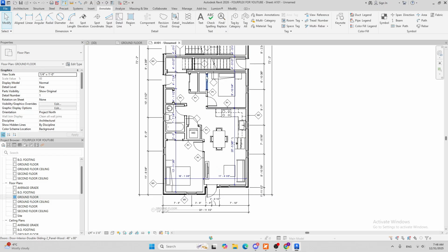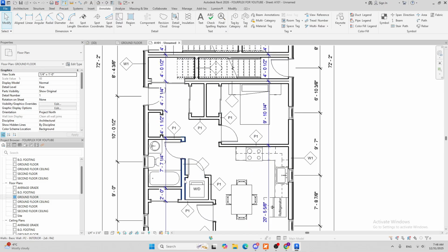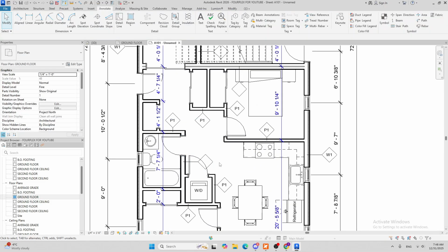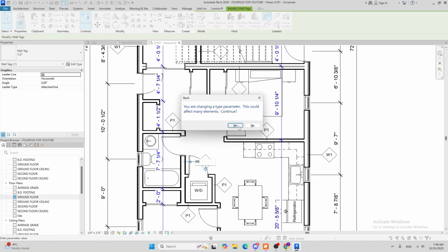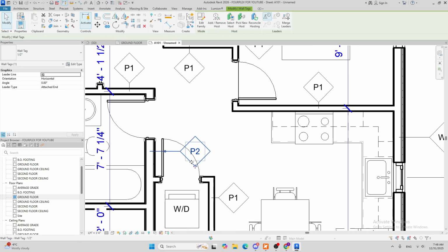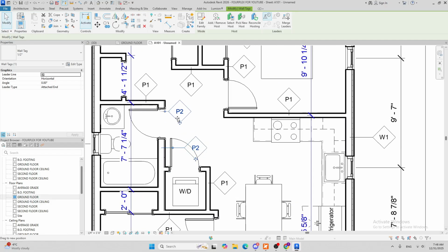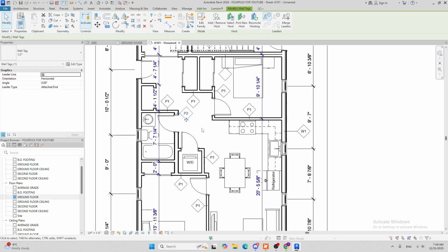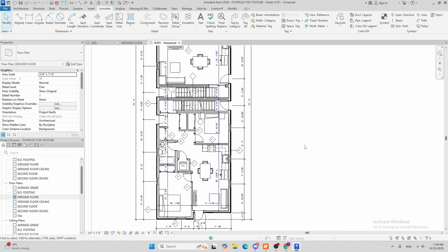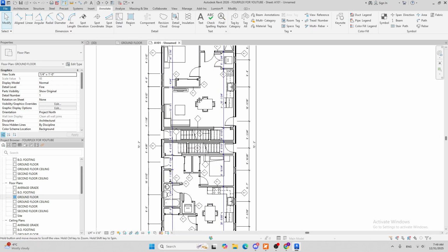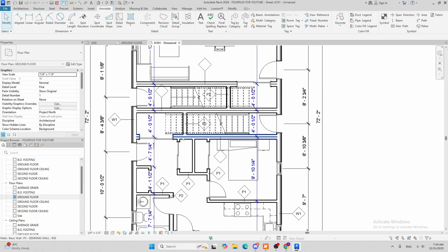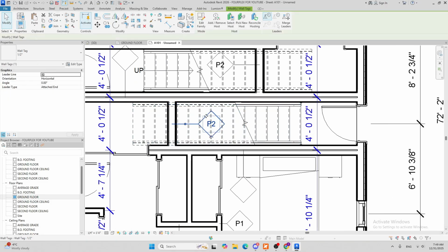So I'm gonna locate the other P's. So this one, that's P2. So I'm gonna click that and click the question mark and type P2 and hit enter. And let's move it to somewhere here. So we have a little bit of space. Is there any other P2? I guess that was pretty much it. And okay, this, yeah, P2 right here. Tab, click, and you're gonna move it closer.